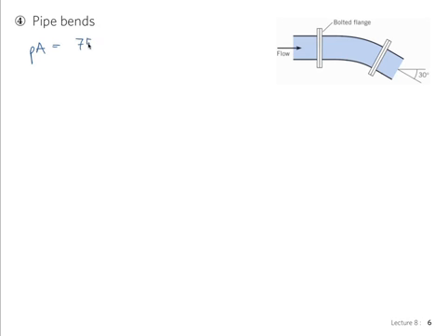The pressure is 75 kilopascal, and that kilopascal is kilonewton per square meter, so remember that we make sure that we've got all of the units correctly. And we have pi r squared. There was a 1 meter diameter, so I'm just taking half to use the radius here, 0.5 meters squared. And that is meter squared, and this is kilonewton divided by meter squared. So this is going to give me kilonewton in the end when I multiply these numbers. 58.9 kilonewton.